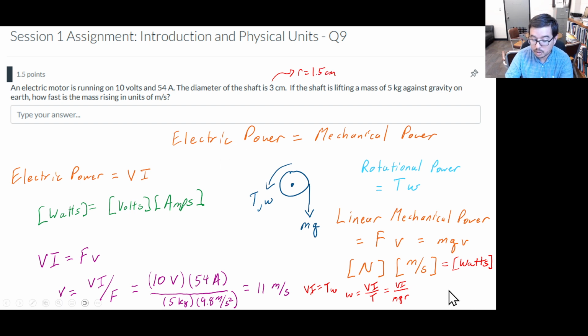Yeah, not very hard, but on exams and various other important things, I'll make that careless mistake. Okay, now we can figure out what the radians per second, or the angular velocity, might be for this rotating shaft, but that is not meters per second. So another equation that we'd have to use, we have to use r again, essentially, and we do another equation of r omega is equal to V.